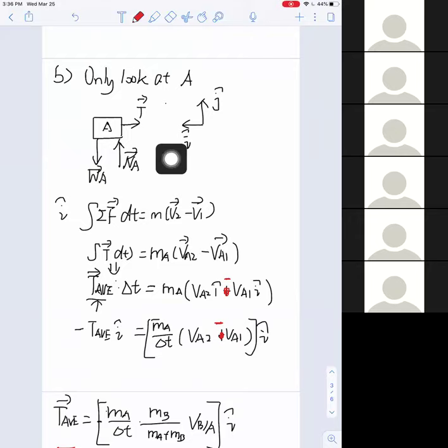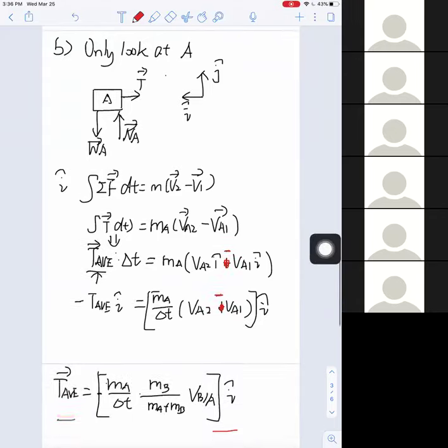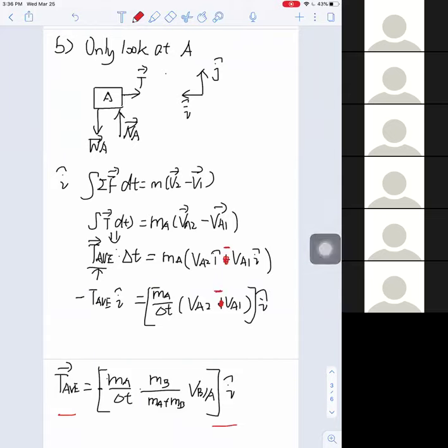So when we did our tension force T here, the tension is on the negative side of I, so I will add a negative sign to show that it's in the negative direction. Also, the result we get here also has a negative sign for the tension in the cable.